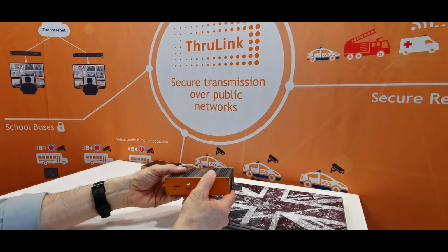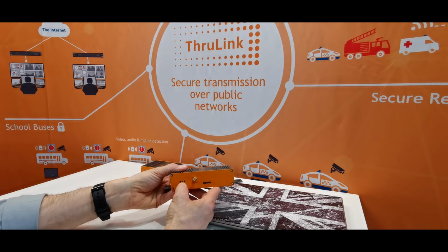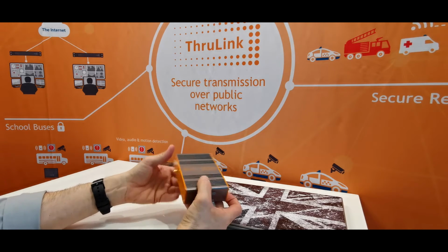On the front side there are 3 LED indicators. First we have the power LED. Then we have the connecting or connected LED which will flash whilst trying to connect and go solid when connected. And then we have the last LED which will periodically flash while checking the connection status to ensure it's still working. Then we have an auxiliary LTE connector. If your network supports diversity, you can use a second antenna for a better quality of service. And then finally the nano SIM slot. And there we have the external connectors of the ThruLink.